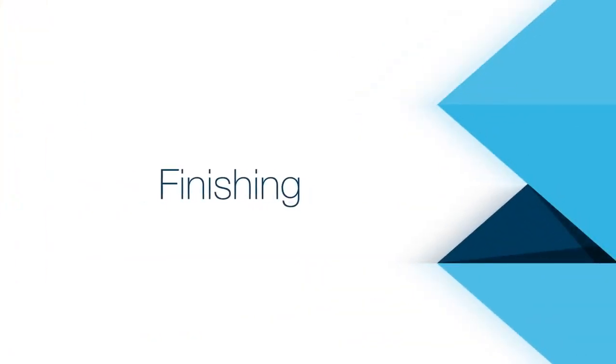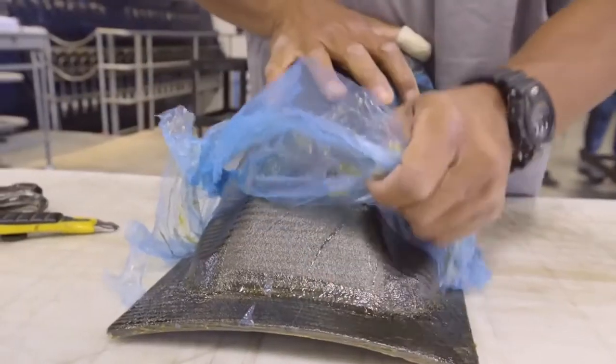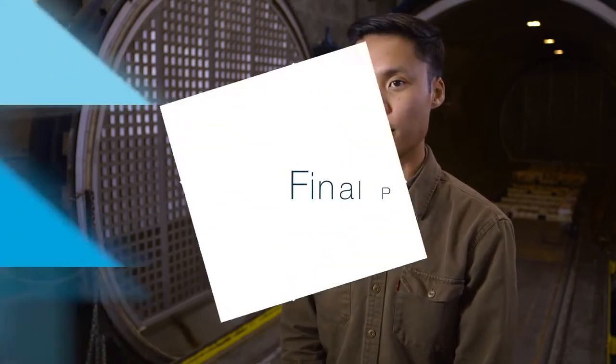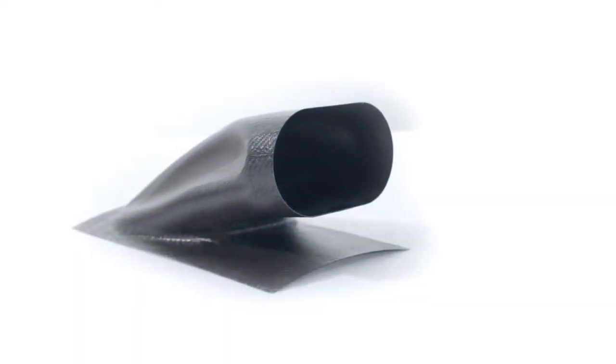After the part is cured, the vacuum bagging materials are discarded, and the tool and the part are placed into a solvent bath for the dissolving of the tool. The solvent bath allows for a simpler and less messy setup when it comes to removing sacrificial tools. After the dissolving process, you have a finished product, which can then be bonded, trimmed, or drilled in the next level assembly.